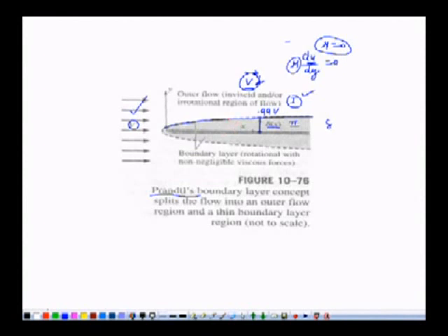Boundary layer divides the flow regime into two categories. The first one is known as inviscid fluid flow or irrotational flow, and the second one is known as real fluid flow, where we have two-dimensional flow, though fluid flow was a one-dimensional phenomenon in this figure. Inside the boundary layer it is a two-dimensional flow, and outside the boundary layer it is a one-dimensional flow having no viscosity. So for case 1, for the outer region, the flow can be analyzed without considering the viscosity. Viscosity is assumed to be 0 and it can be solved very easily.